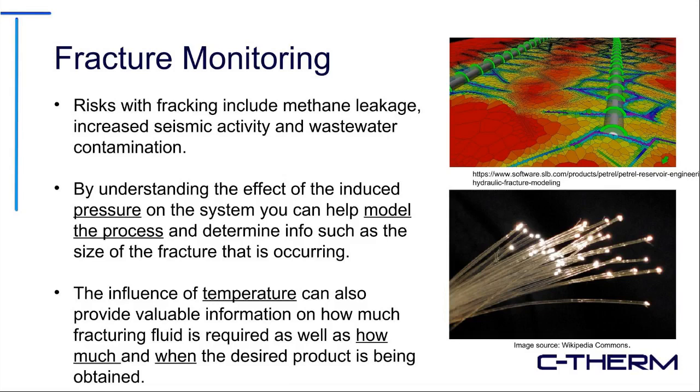How you do that is through understanding what you're actually dealing with and how the process you're introducing into the system will change its natural state. One example, especially in fracking, is that you're introducing massive pressure into your system to fracture the surrounding matrix. One way to see what's going to happen is to model the various geological formations based on your induced pressure, to see the size and location of where these fractures will occur, looking at some of the thermal stress or thermal load that will be introduced into the system as well.